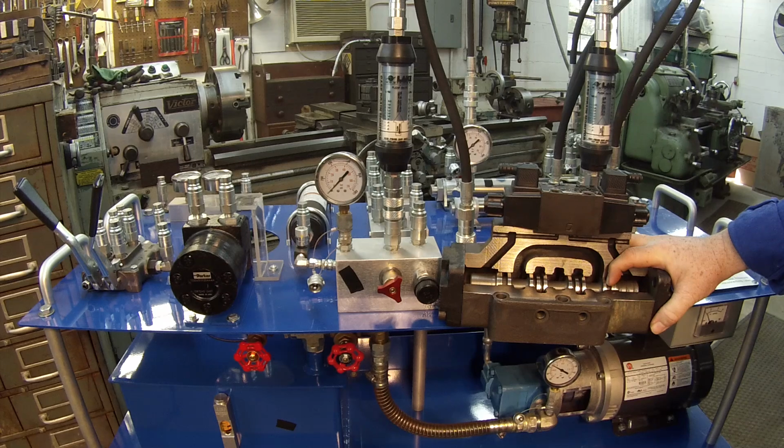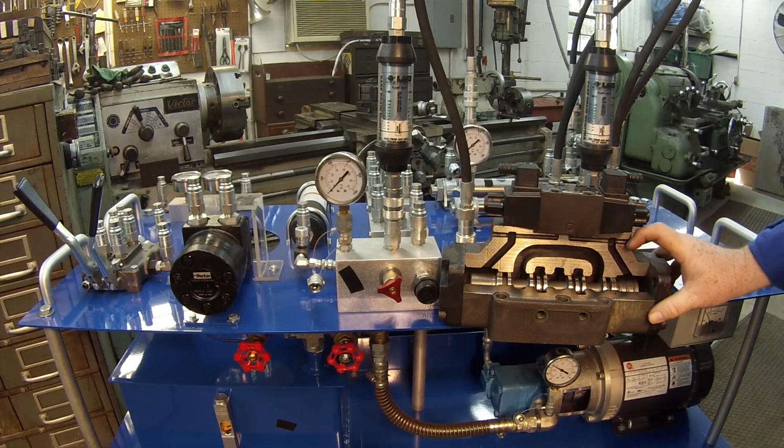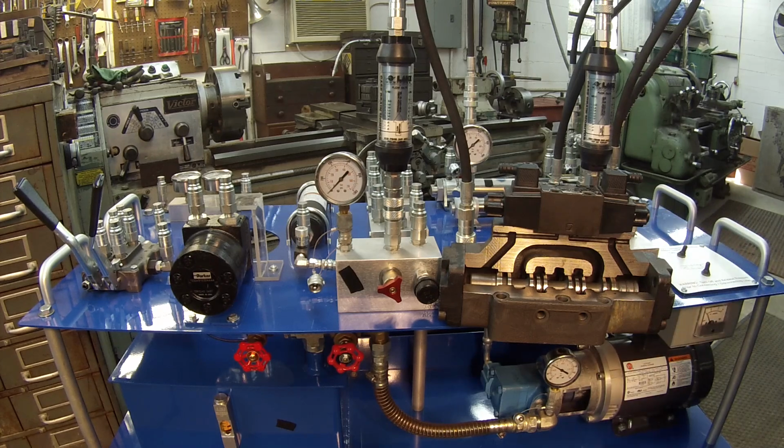Okay? One of the things that I often hear when I go in and out of facilities is, it's mechanical, no it's electrical, it's mechanical, no it's electrical. On these directional valves right here, this is called a manual override. So at 2 o'clock in the morning, if your actuator isn't moving, you can get a push pin or a little Allen wrench and push that right in, and it'll manually shift this valve. If your actuator moves or your motor starts turning, then that tells you that you've got an electrical problem. That's one of the biggest things I run into out there at 2 o'clock in the morning.